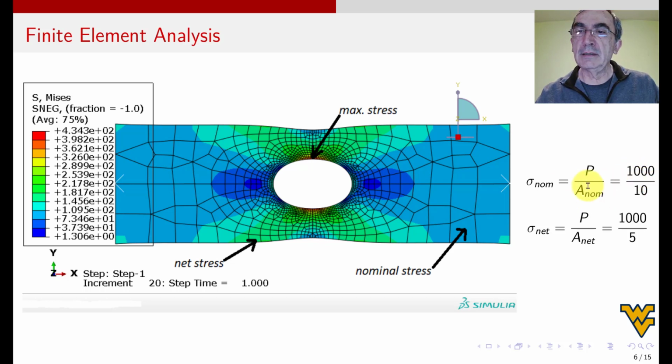So that's 100, right? So blue is 100. And is that true? Yes, because this is the blue. And then it goes between 73, yes, there is a 1 here, to 109. But believe me, it's 100. It's not 73 and it's not 109. This is because of the artifact of the contour plot. But because mechanics of materials tells me it is 100, I trust it's 100.